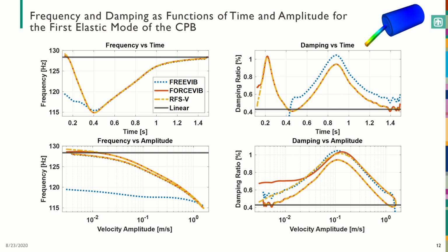And one last thing about this, you see how there's a gap in the damping curve between the ramp up and ring down portion in the bottom right plot. We think this is probably due to a small error in the scaling of the force, either from a sensor calibration issue or the mode shape coefficient used to form the modal force being slightly off. Scaling the force by even a couple of percent can shift the damping curve quite a bit.